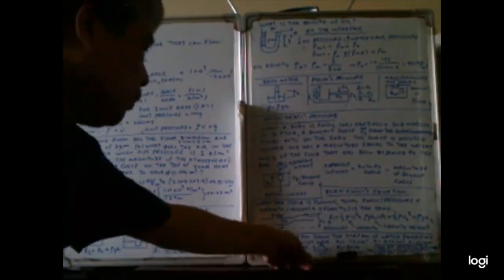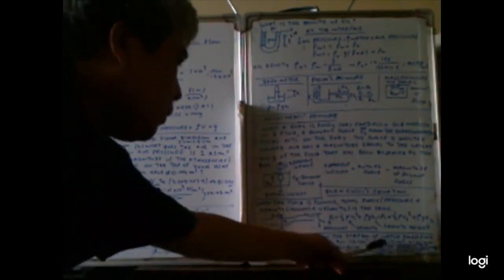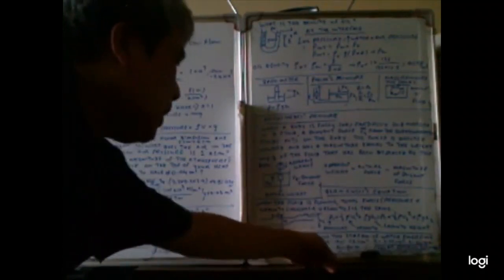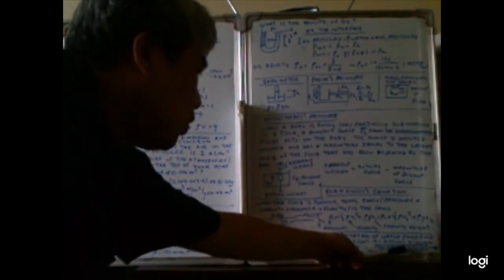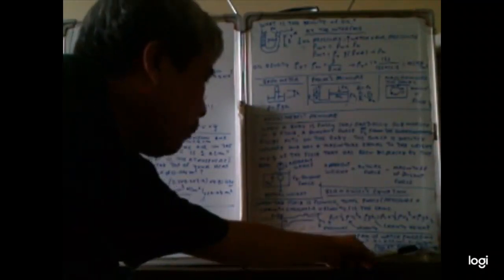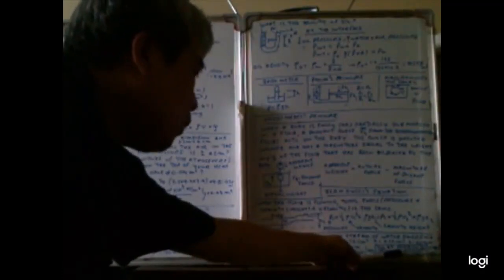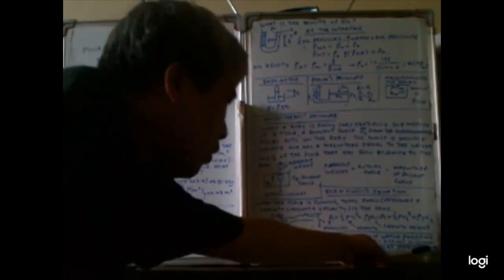V squared is V0 squared plus 2gh. So V0 is equal to the square root of 2gh A squared over A0 squared minus A squared. So 2 times 9.81, times A is 0.35 squared, over A0 is 1.2 squared minus 0.35 squared. So you get 0.216.